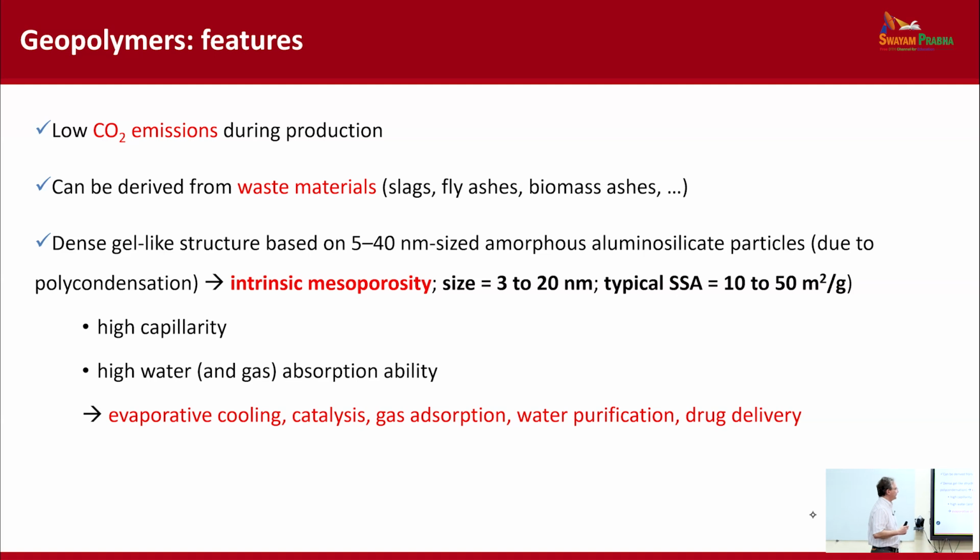And what you obtain is a gel-like structure. Since you are carrying out condensation in alkaline environments, similarly to, if you wish, sol-gel systems, you obtain amorphous aluminosilicate particles that are bonded together. And this leads to intrinsic mesoporosity.